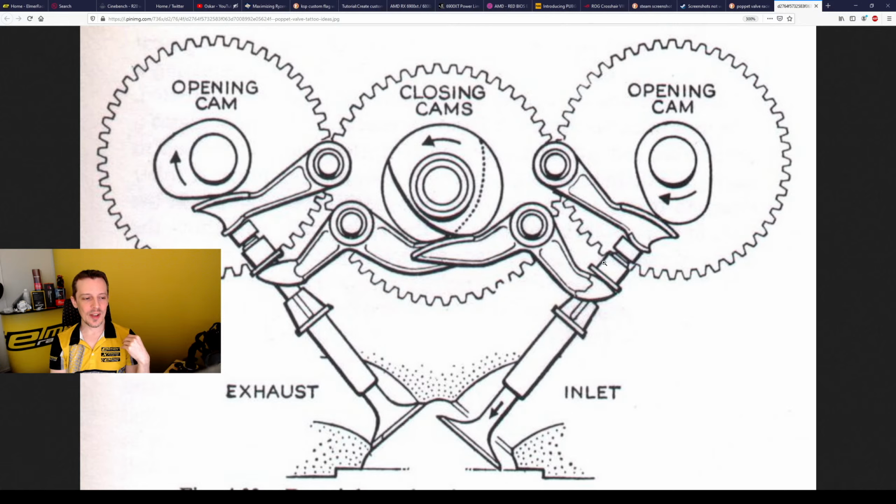You don't really want to have dead areas, because in that area the valve can bounce between the opening and closing cam, and that's probably not ideal from a longevity standpoint, because you really want to be maximizing the accelerations opening and closing, and the transitions between the opening and closing cams. But you still need to have some kind of clearance, because you can't have binding.